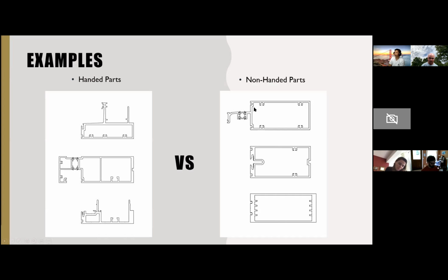I try not to explain to people that you can have a two gasket or one gasket, because it could be a handed part, but sometimes has two different gaskets on it. So I don't want to confuse anybody. So the good way to understand is handed part with one daylight opening, or say it faces one daylight opening, and non-handed part is two daylight opening sides.